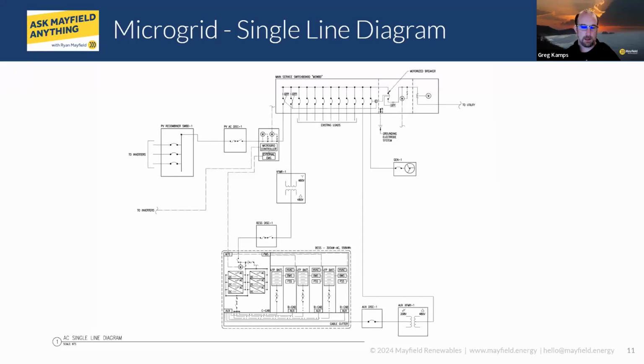And then down on the lower right, just to talk about what that is a little bit, the controls and some of the other systems that are part of the BES need to run on 208. So there's another separate feeder there to feed those loads. There's a 480 to 208 transformer there, and a little disconnect for those loads in the BES. That's often for HVAC units, one of the more common things we need to power with an auxiliary transformer.